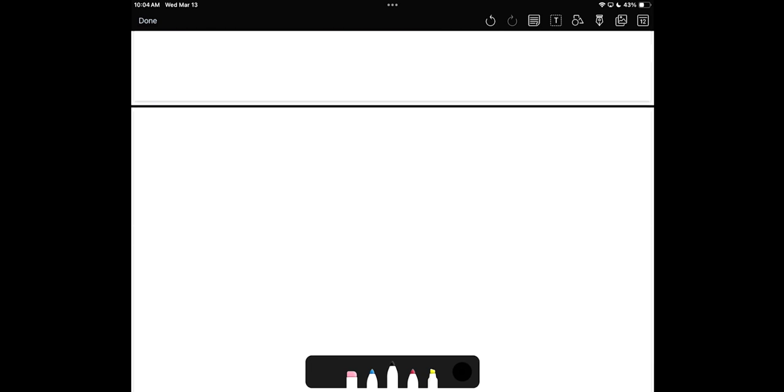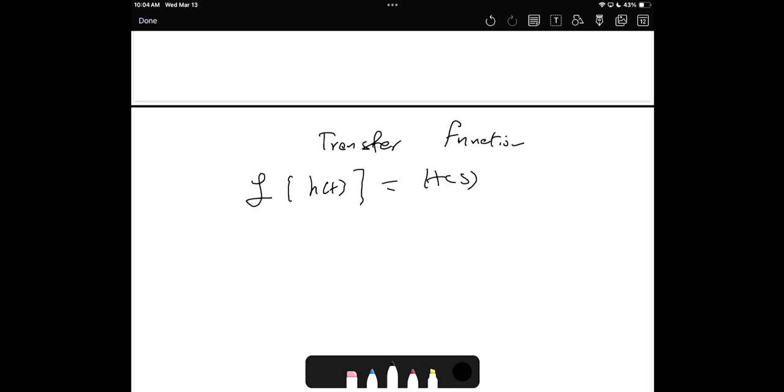Now the transfer function, what's the transfer function? If I ask, what's the transfer function? We already discussed this last lecture. What's the transfer function? Yes? It's a Laplace representation of the process. Yes, it's the Laplace representation of the step response. Okay? So it will be H of s. And there is also another way to find the transfer function. Basically, it's the relationship between the output over the input of the system, and it will be in the Laplace domain: Y of s over X of s.